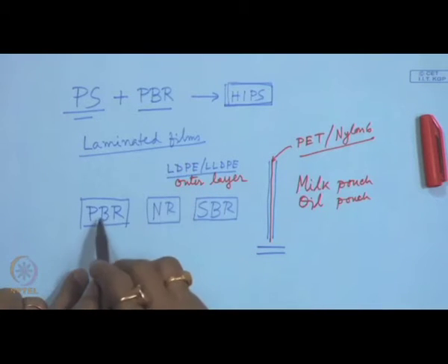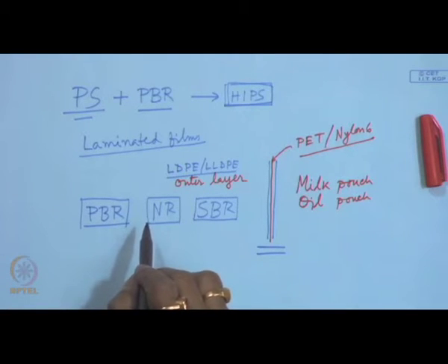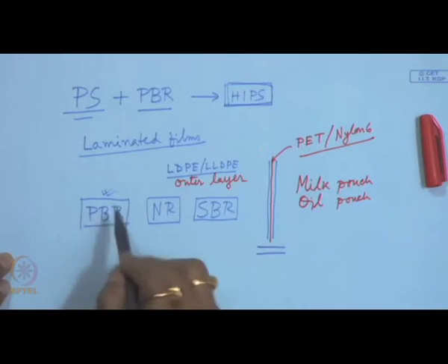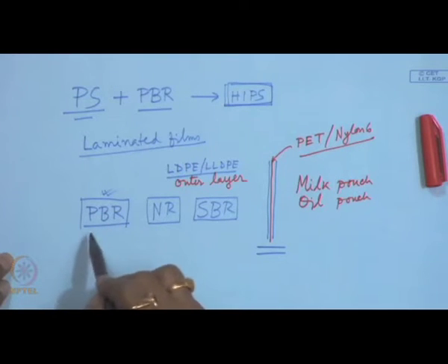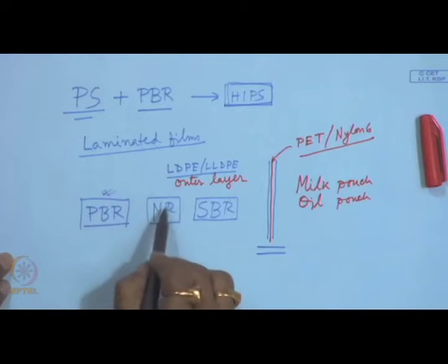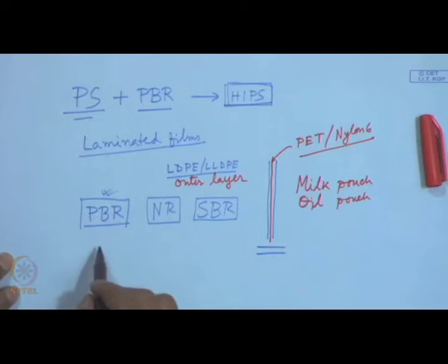So, processability, I mean the compounding of this polymer, as well as shaping and fabrication of the compounded polybutadiene rubber with some other additives, that is not good. So, in order to improve the processability, we can use a little amount of natural rubber or SBR with this polybutadiene rubber. Similarly, processability of other thermoplastics, polyolefins or other polymers, say condensation polymers.